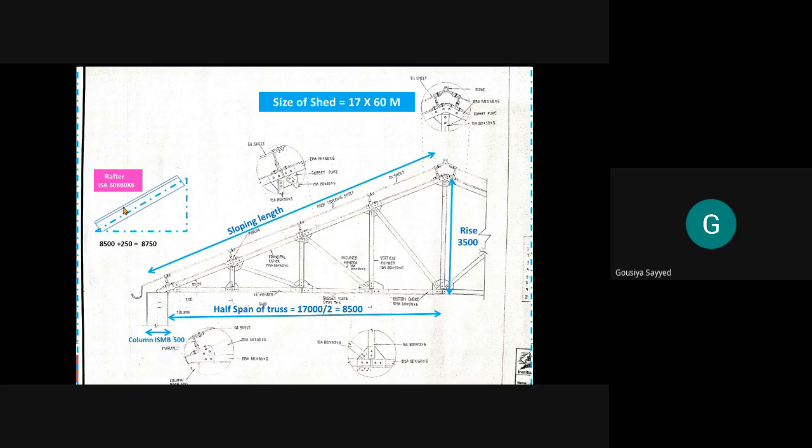Just simple: you have to draw a rectangle in such a way that 30 mm is above the center line and 30 mm below. So overall it is 60 mm, one side of the angle section, and you have to show the thickness of the angle, 6 mm. Are you getting how to draw the rafter on this truss?